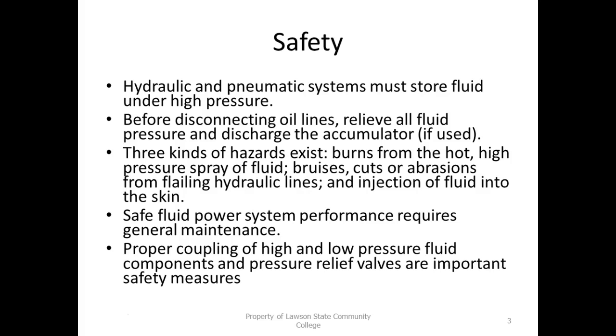Hydraulic systems run extremely high pressures, and when you break those lines loose, that pressure is looking to push that fluid out in different directions. And we've had people where it comes out with so much pressure that it literally shoots that hydraulic fluid into their skin, and then it gets really infected because it's not good stuff.